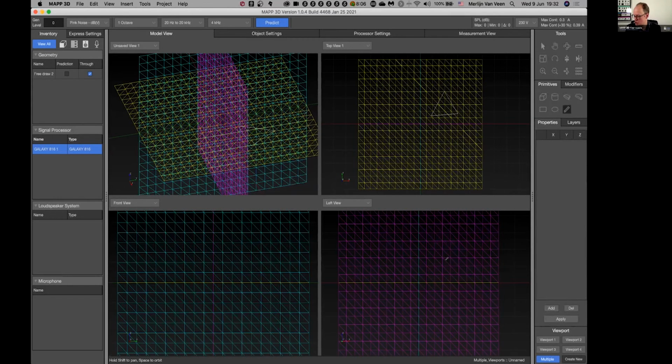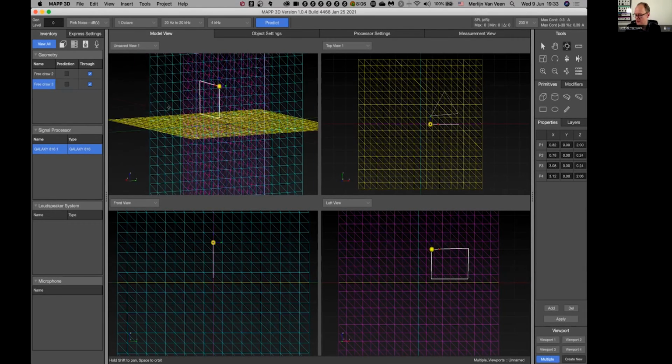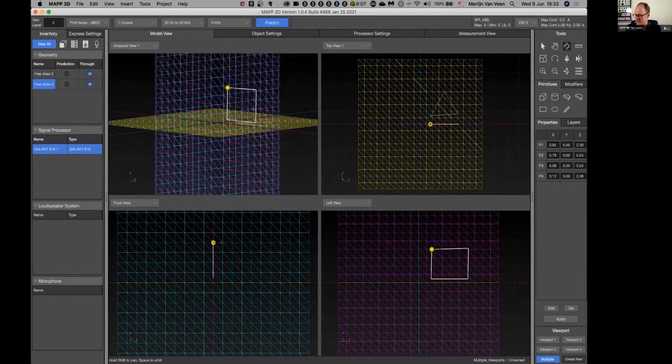So now we're going to add another shape. Why don't we start drawing a rectangle in the left view? And if I start drawing a rectangle in the left view, notice that it ends up living in the purple plane. I want to finish this shape. I'm going to hit the C for close, and that completes my rectangle. And notice that this snapped to the purple plane. This snapped to the XZ plane.